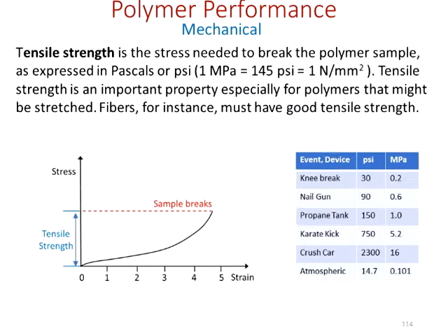Where does it break? It breaks there, and that gives you a measure of the tensile, and that value is reported. Okay, so it's put in the instrument. That you'll learn, the instrument is an Instron, again, a device for measuring tensile, for stressing and straining the polymer, and you get a value. Okay, so you get that value, essentially that height, if you will, from the horizontal, and the distance from the horizontal, and that is your break point, the tensile strength.